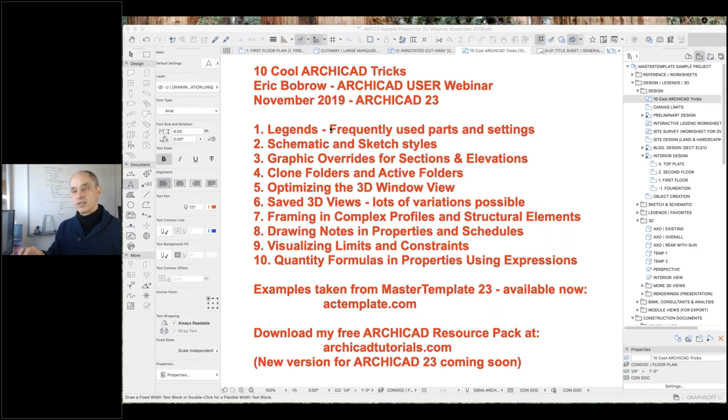This is this type of an electric receptacle or this type of lamp, etc. So a legend is something that you can see to understand the graphics of the presentation. But if you place the elements on screen in your ArchiCAD environment using the same tool as you use to draw those elements in the first place, so they're not just 2D graphics, they are walls or objects, then of course you can use the eyedropper.